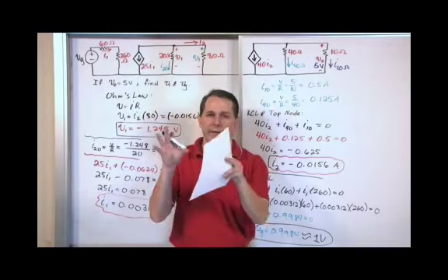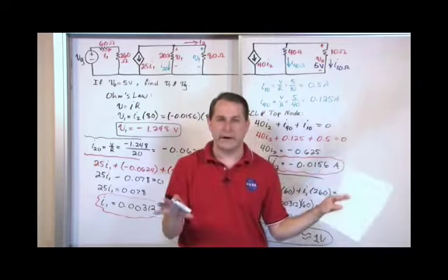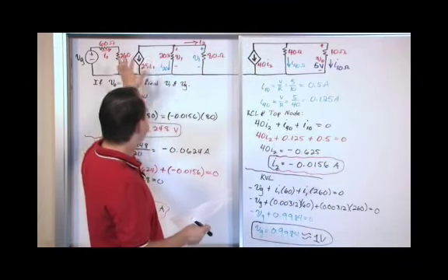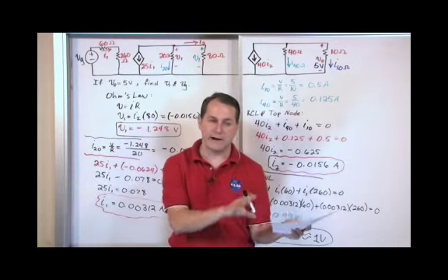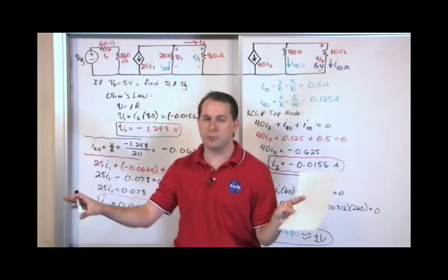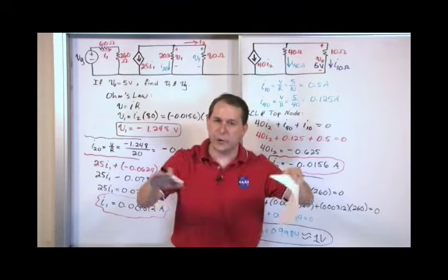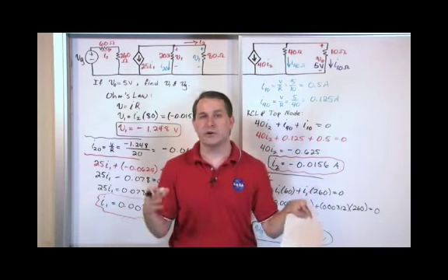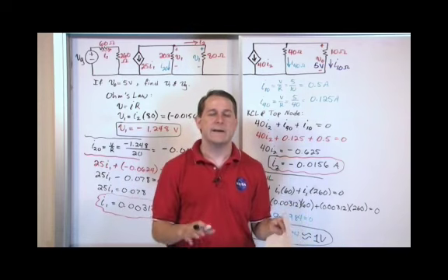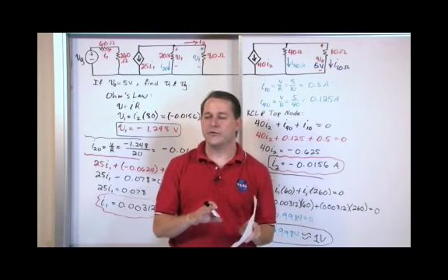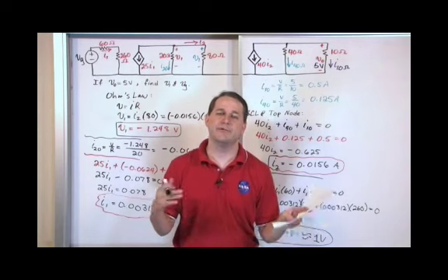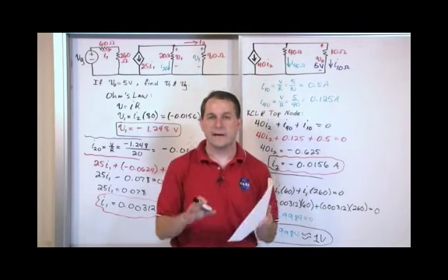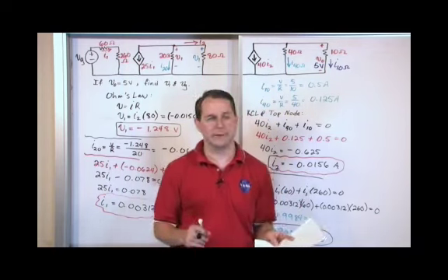It's more of separate circuits that are operating independent, more or less, but they're still dependent on other parts of the circuit, much like a transistor amplifier might depend upon current from somewhere else. But their base voltages and their operating voltages, the low part of those potentials, are tied together. It's called common ground. We talked about that, and that's important. There's a whole theory and discussion we could have on that, but suffice to say that you really should always do that when you're designing complicated circuits because it prevents other issues from cropping up.